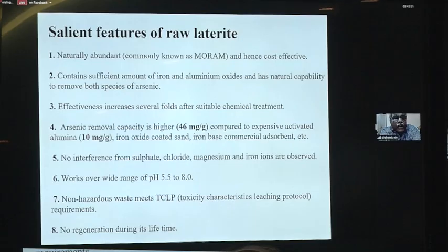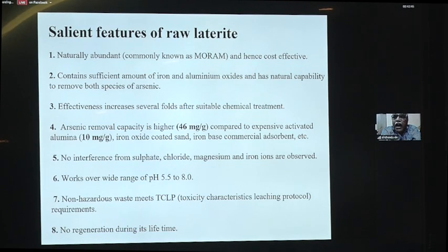There is no interference from any competing ions like sulfate, chloride, magnesium, iron, bicarbonate, carbonate, whatever is present in the groundwater. It works in a wide pH range between 5.5 and 8. The most important feature is that it satisfies the toxicity leaching protocol. That means once its life is over, the media binds arsenic by strong chemisorption. Even if you leave it open under normal atmospheric conditions, the bound arsenic does not leach out and recontaminate groundwater.